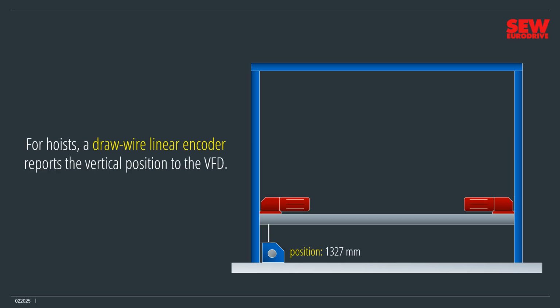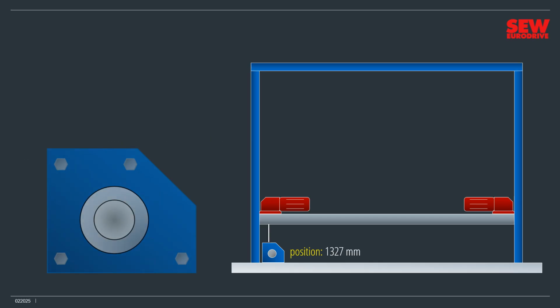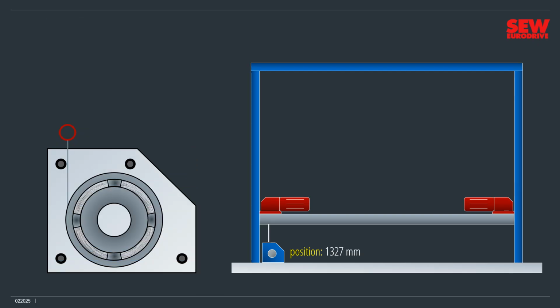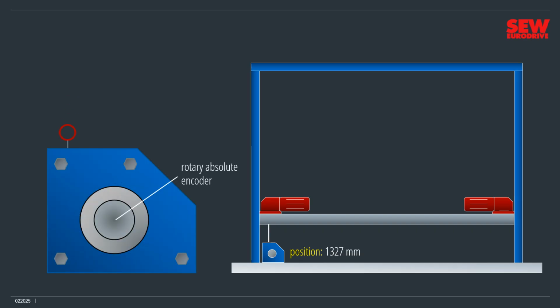Perhaps you're wondering how it works. Let's see. Taking the cover off reveals a spool of wire inside. It's spring-loaded, just like a tape measure. As the hoist moves up and down, it pulls the wire in and out, causing the spool to rotate. A rotary absolute encoder mounted on the cover and attached to the spool generates the positions. Pretty simple and rather clever.